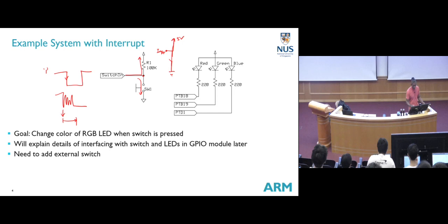Same thing for your LEDs. If I don't put a resistor, of course, very nice, very bright, nice to take a video and put on TikTok. But then what happens? After a while, the whole LED will burn. So it's important why we do certain things. Even though the resistor is limiting the current, it is there to protect the LED.